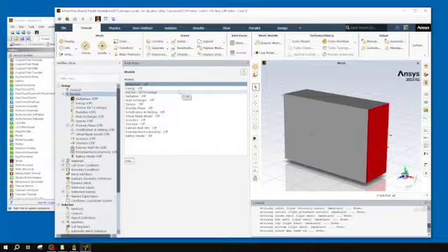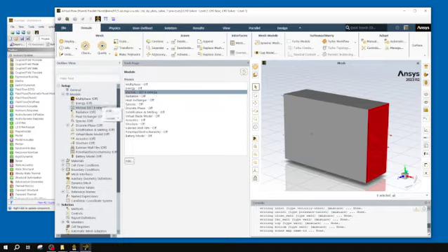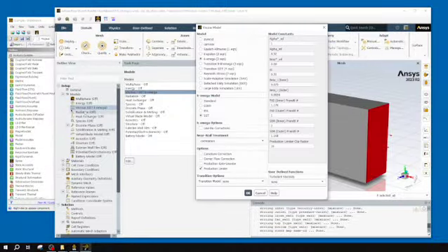I like the viscous model. If you really want to change things, I suggest right-clicking what you're changing in here or double-clicking it. It just opened on the wrong tab. So I double-clicked my viscosity for my SST K omega, and I have a couple things that I can change. If you're incredibly familiar with the equations and formulas, you can actually change the coefficients if you have a custom one.